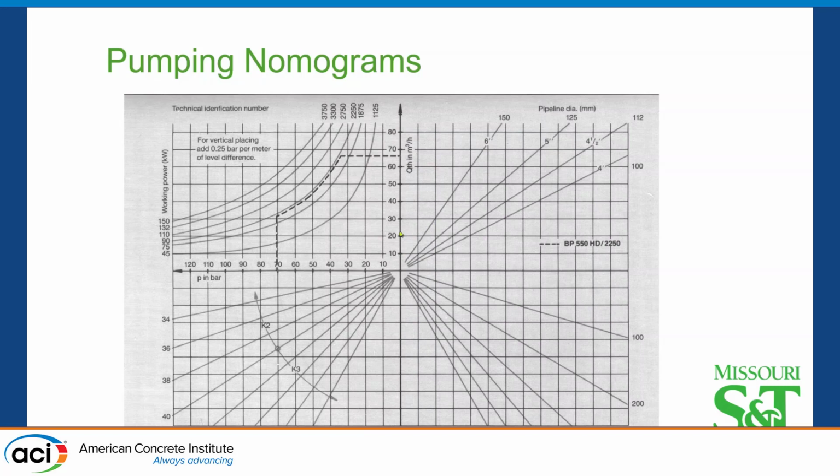So you start with flow rates, then you have your pipeline diameter, you look for the crossover, then you go down when you have your crossover, and then you look at the proportional length, because there are some correction factors for curves and for bends and reducers and so on. And then you cross over again, and then you have a qualification.